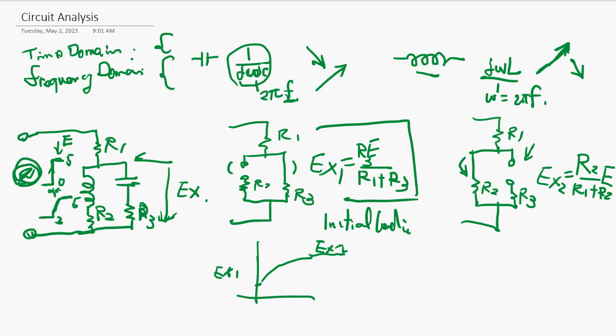So this transitional transient voltage is going to cause the output like that. So you can tell pretty much by using short circuit and open circuit for the impedance. Okay, so this is good for finding the initial condition for solving the differential equation.